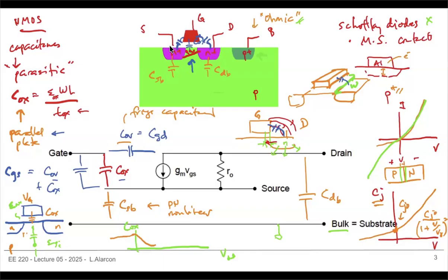But what happens as soon as you get closer, for example, to the threshold voltage? Now you're forming an N channel. And now most of that cap is just going to be Cox, because if we assume that your source is also grounded, that's pretty much most of your cap. And then it starts going up, mainly epsilon times area over Tox, Eox, and that's the same thing here.